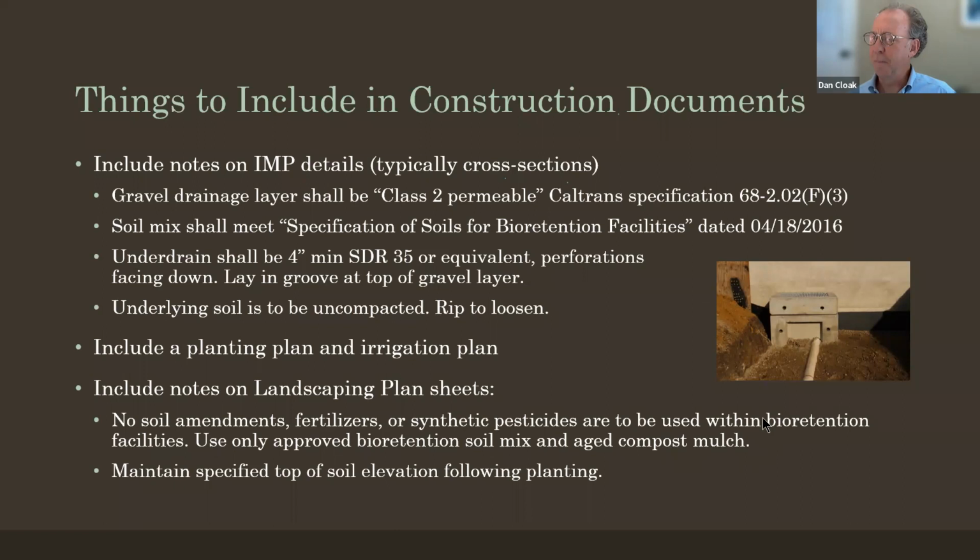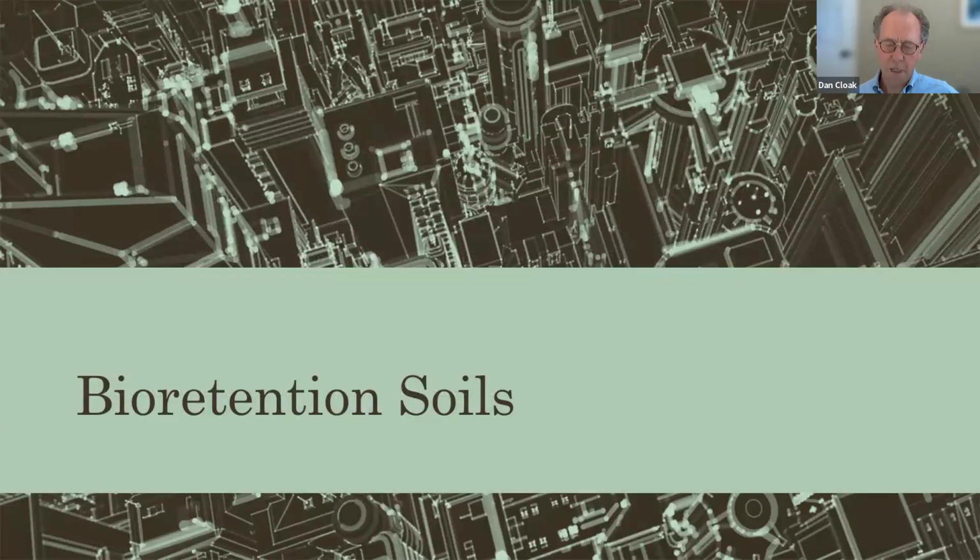And so the reservoir ends up filled up with mulch or even with soil, and so you don't get that 6-inch reservoir. So that needs to be communicated through the landscaping plan, and make sure the landscaper knows it.